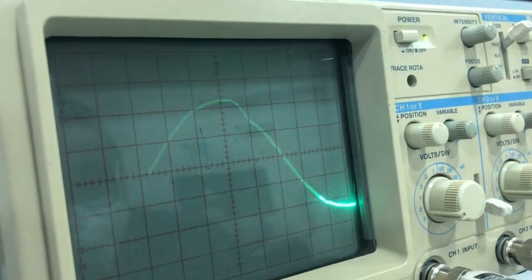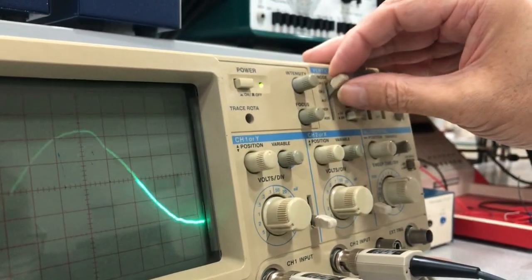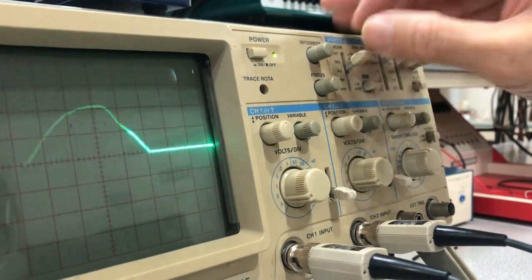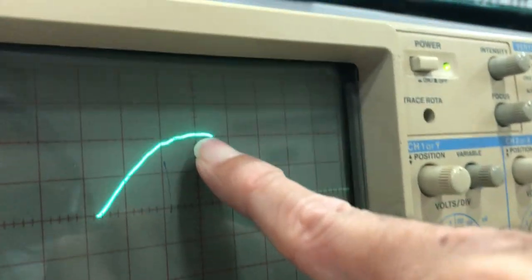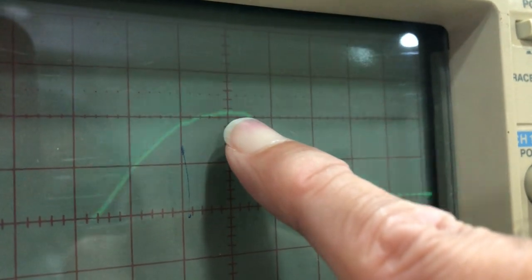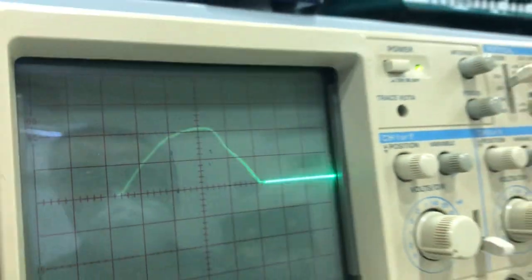Okay, so I made my input peak voltage. Now my channel 2 did not go down from the 11 exactly to 10. So I don't have a 1 volt drop. Okay, I want to measure this more precisely.